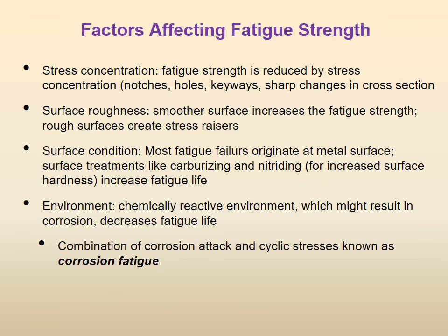So we have done some of this earlier. Remember, K1 is equal to sigma root pi a. So from K1 we go to K1C, where the sigma, the applied load, has to be more than a critical load, or the a becomes a_c, the critical crack size, and so on. But this time it is for fatigue loading.